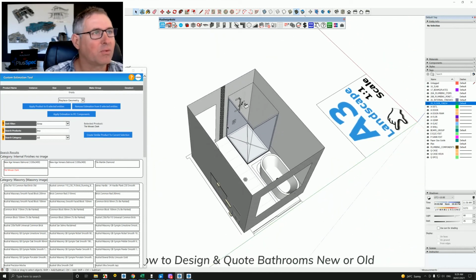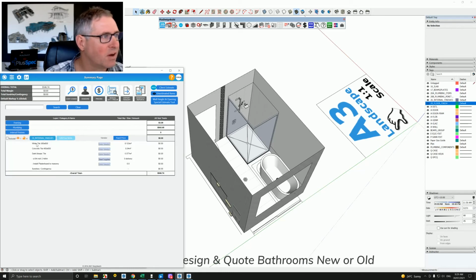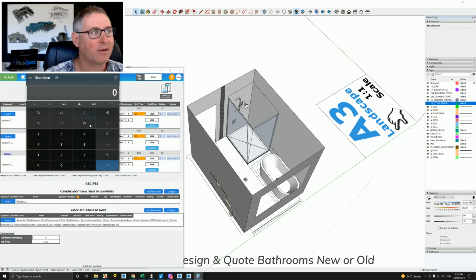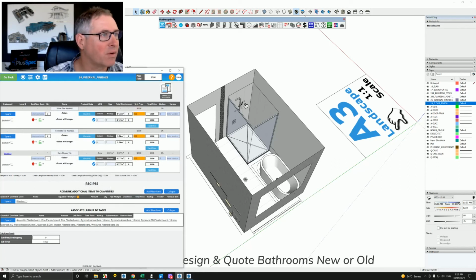Now if I did a bill of quantities now, guys, take off. You'll notice I've got internal finishes. I've now got the tiles, the amount of quantities of tiles, and for instance here I might actually go, how many tiles are there per square meter? So if I grab my calculator up here and say 0.3 times 0.6 equals, there's 0.18 square meters per tile, right? So I could then divide that by a meter, or I could just say how many square meters per unit. So if I go in here and go, how many square units, it'd be 0.18.